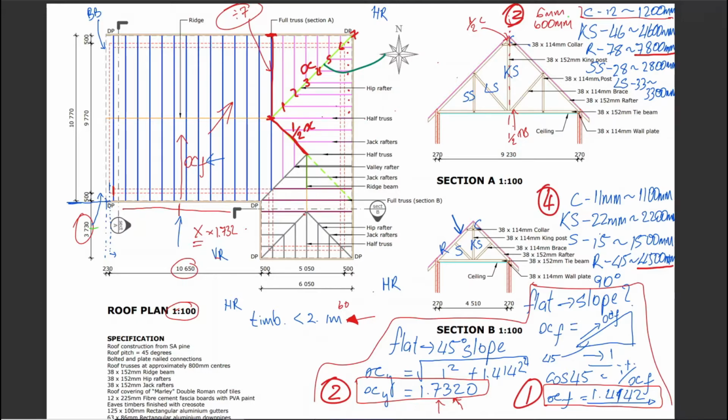So what this orange line is saying, that's a center line, okay, or a ridge. And previously I put it in inverted commas. Yeah, it's a ridge, but it's nothing physical. Not yet, at least. And the same is true for this side. Ridge, nothing physical. But they've indicated nicely here that in green is a ridge beam, and it starts there, ends there.